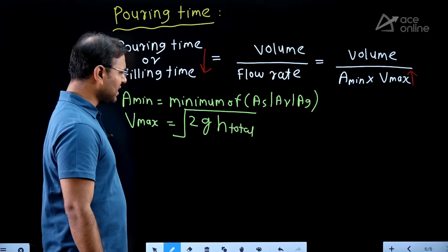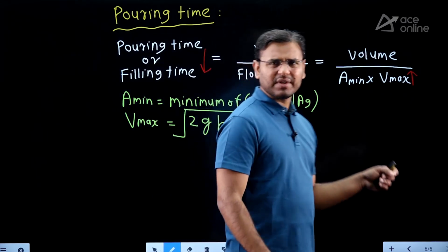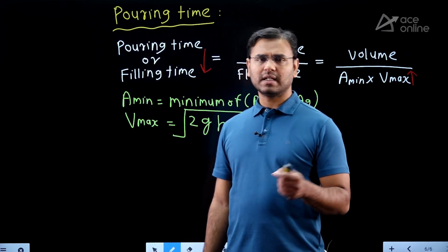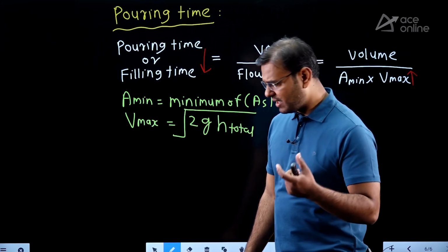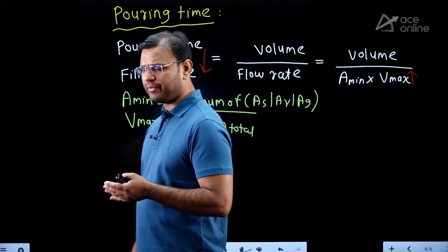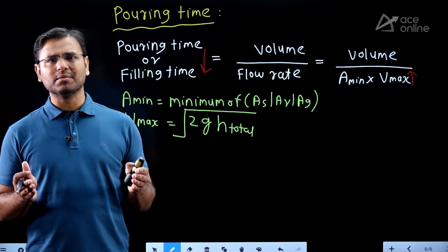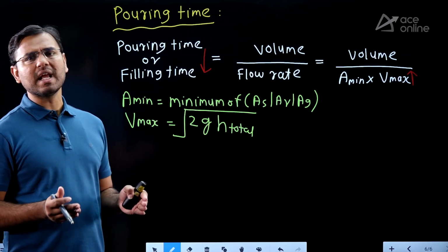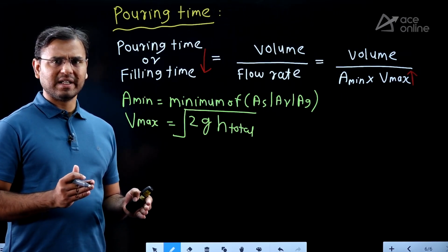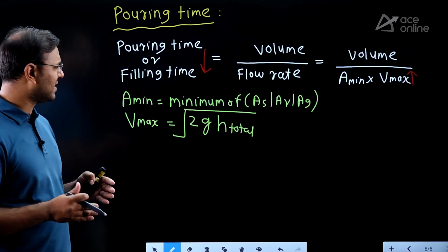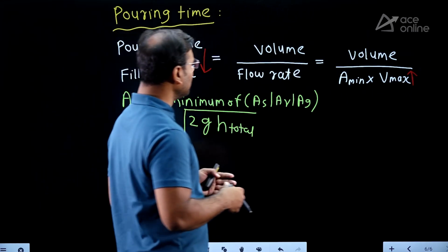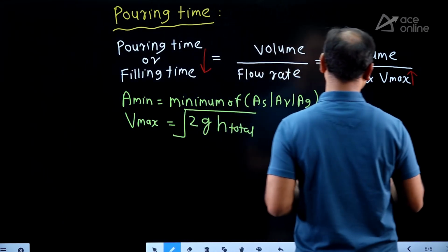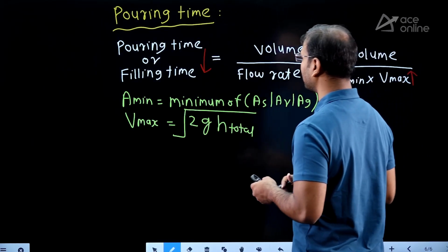Here, guys, we cannot change that area. Why can we not change the area? Because when we manufacture, we make the mold and fix the bottom area of the sprue, and the cross sectional area of the runner is also fixed. Therefore we do not change those terms. But the velocity we can increase. If we increase the velocity, then the pouring time is going to reduce.